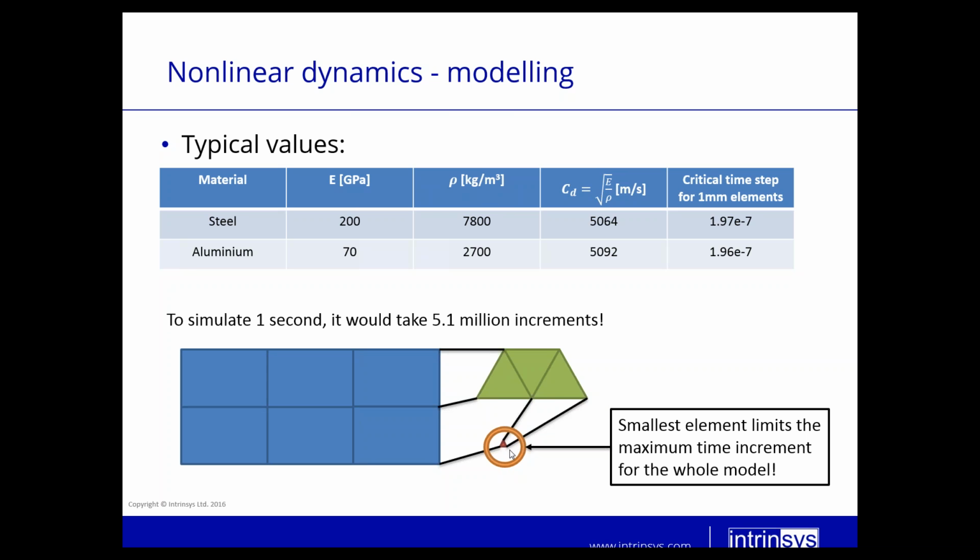Because if you see this very simple example, you can have nice large uniform meshes, but if you have a few tiny elements, because the whole procedure is limited by the smallest time increment, even one of these can potentially reduce your time increments to E-9, E-10, even lower, in which case it can take about 1,000 times more time. So if with an E-7 increment you might finish your simulation in 1 hour, if you don't design your mesh well, it might take you 1,000 hours to run it, which is clearly something you don't want, because you will never be able to solve your problem.